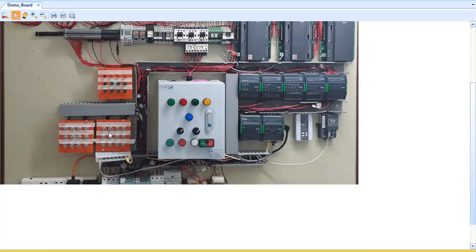Then my computers in my BMS room, my server and my workstation, will be connected to the network switch, so that the link from the BMS room to my automation server, and my automation server can communicate to other controllers using the BACnet MSTP network. So BACnet MSTP, TCP over IP, then to my computers.